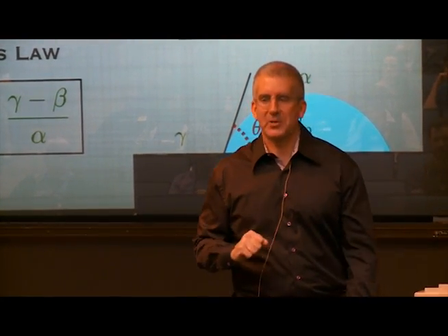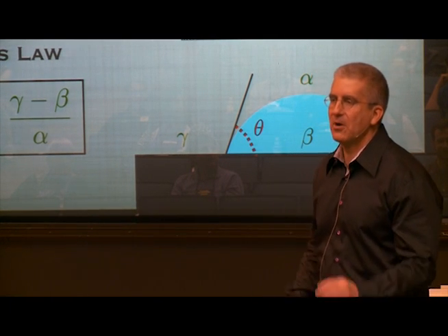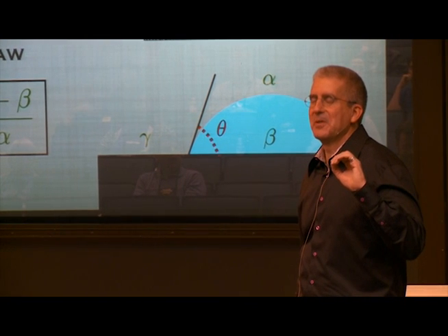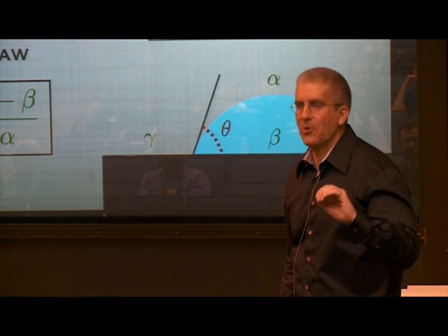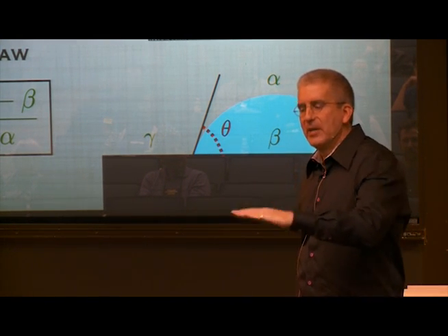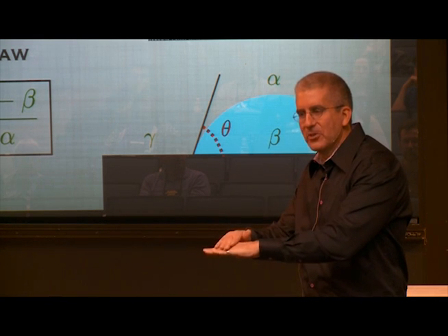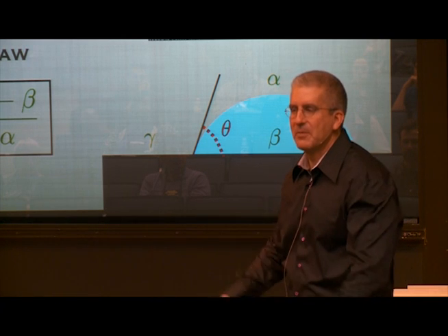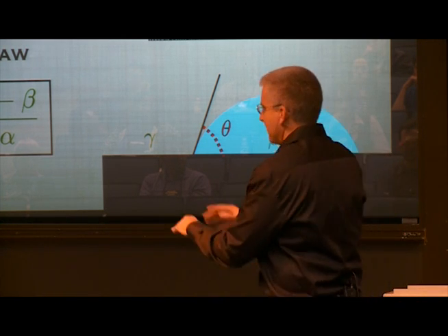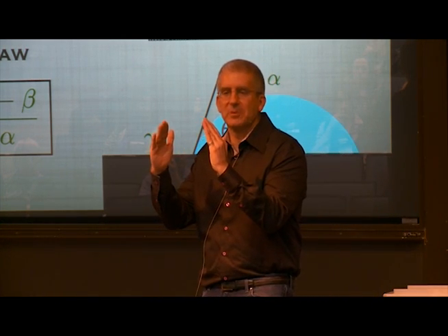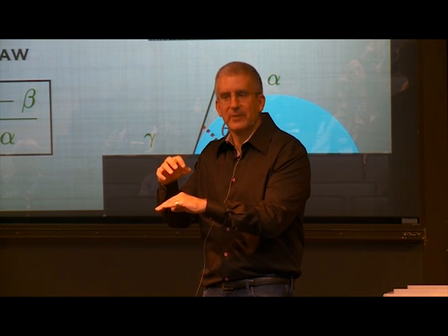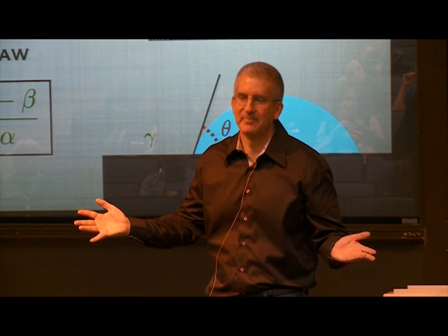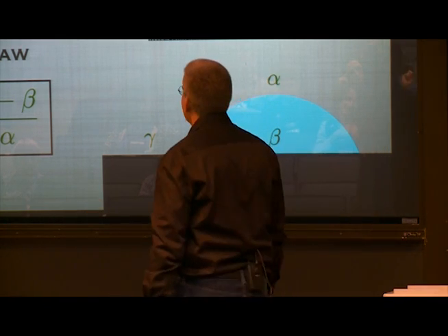What happens when you wax the car is that you increase the energy cost per unit length of the interface between the solid surface and the fluid droplet. Since that becomes energetically more expensive, the contact angle becomes steeper and steeper. The droplet comes off, the water flows off the car naturally, and it looks fabulous. Okay, so that's why we wax our cars.